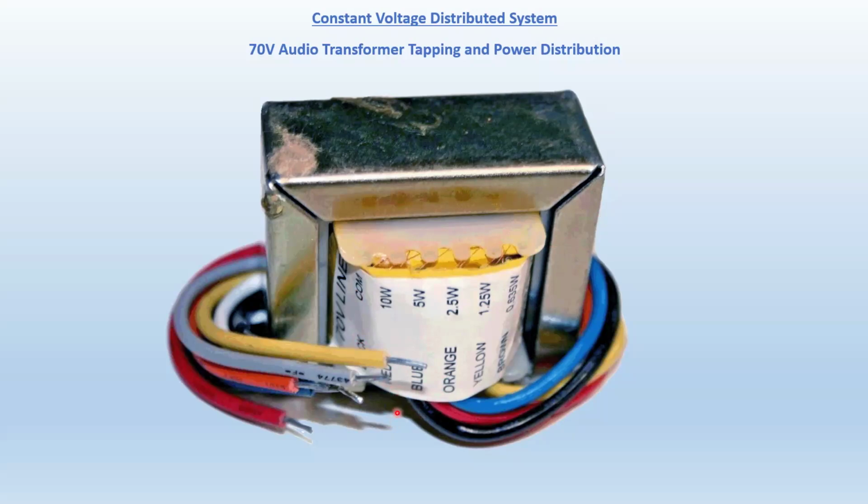So you're going to use one of those, the black, and the other one you're going to choose depending on how strong you want that speaker station to be. Do you want to tap it at 1 watt? Because 1.25 is considered 1 watt. 1 watt or 2 watts or 5 watts or 10 watts, which means if you use the yellow, black, and the yellow only, and the other ones are not connected, then the transformer, the speaker station, is going to use 1.25 watts at the full volume setting of the amplifier, and so on.